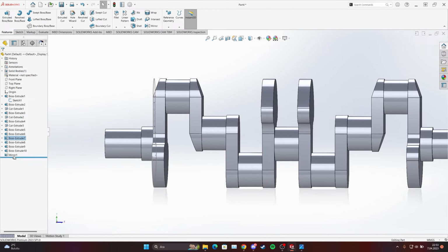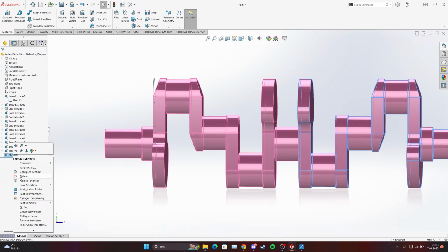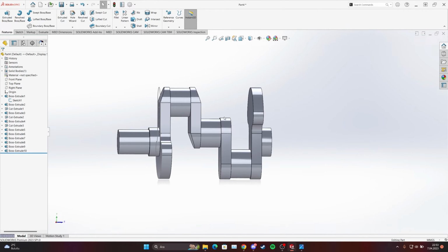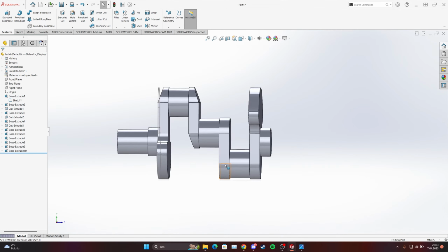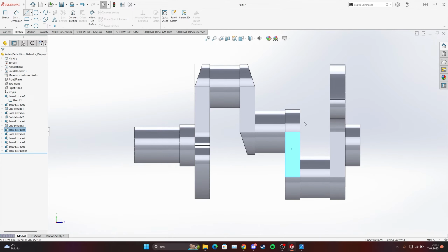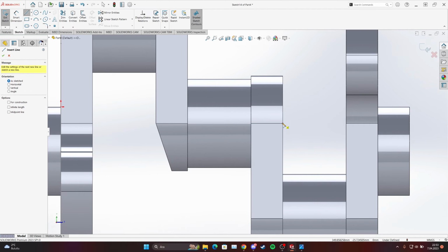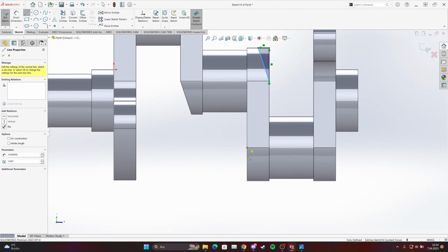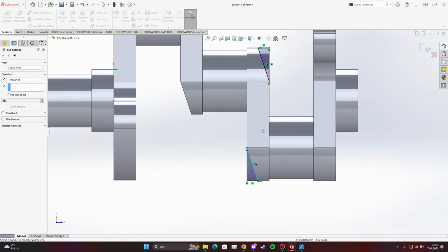But before mirror, you can delete this like that. Just delete this one. We can also cut here and here, so it will look better. Make it normal. Come to sketch. From that point to that point, and to the middle point, and come back to this one. So finish the triangle. And from that point, the same process to here. And then just cut it.